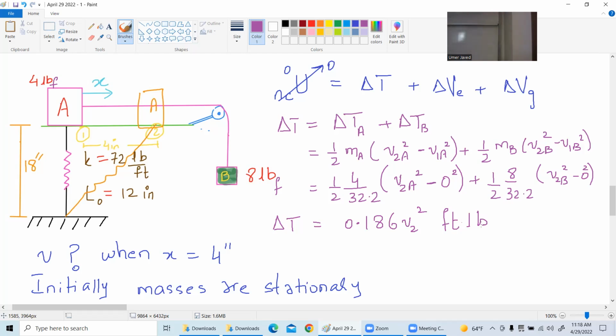Why did you divide 4 by 32.2? To get the mass. But we have the mass, right? Right. That's why I wrote F. That's pound force. That's weight. And that's why the system is confusing. That's why I specifically put an F. If I had put an M, LBM, that would have indicated pound mass. Okay. What were you asking, sir? We were discussing the answer. Sure, okay.